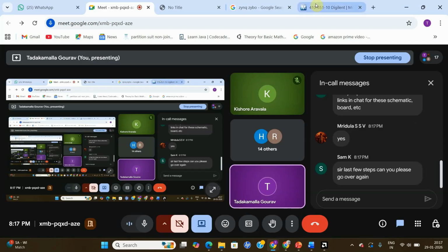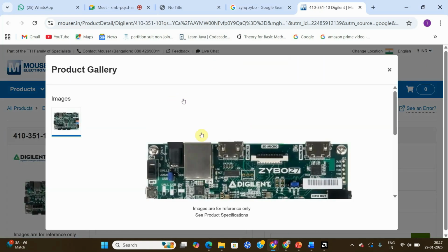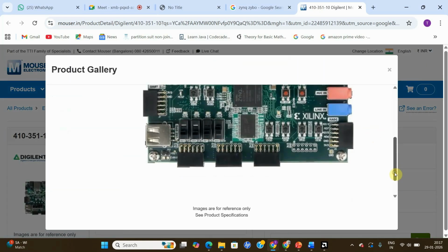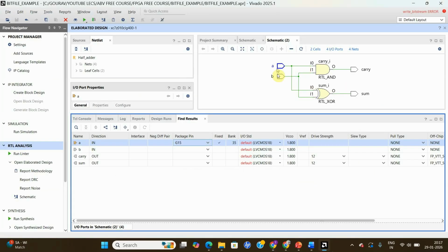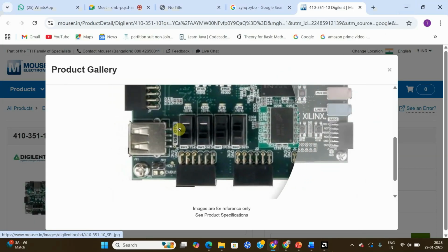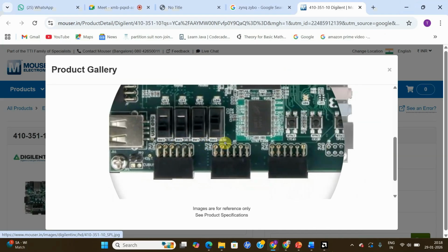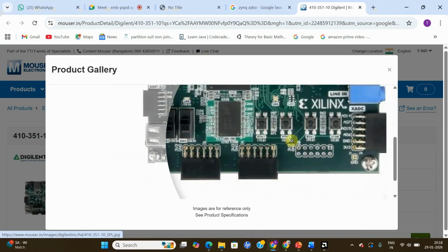Okay. What I am basically trying to do is first select which input I should connect to a switch or a push button. Here in my diagram, I have two inputs. I need to connect each to either a switch or a push button so that they will act as an input of my FPGA. For my switches, there are numbers like T16, W13, P15 and so on, and for my push buttons also, there are numbers.